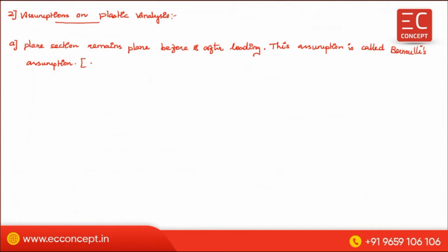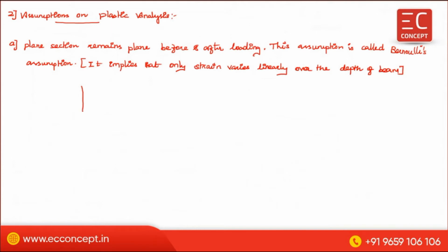This assumption, plane section remains plane before and after loading, implies that strain varies linearly over the depth of the beam. So this is the initial beam.